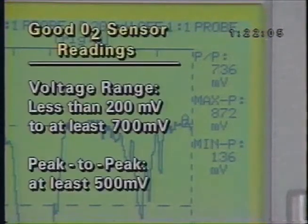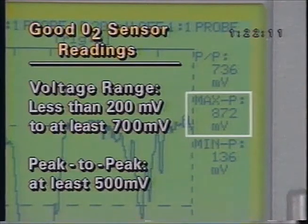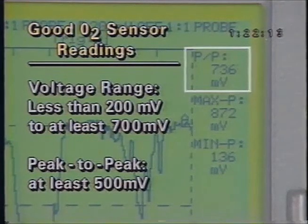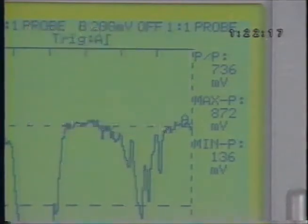A good oxygen sensor on a system that's working properly should range from less than 200 millivolts to at least 700 millivolts. So the peak-to-peak voltage should be at least 500 millivolts. If the oxygen sensor voltage doesn't range between these levels, the sensor could be bad or the system may not be working properly. The setup for this exercise will be useful in the shop for diagnostic procedures. Save it to Setup Memory 7.